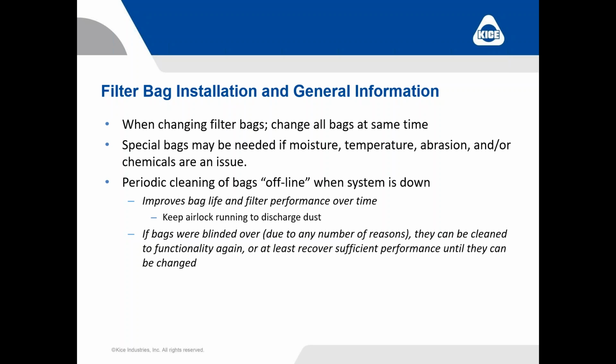And what that'll do is at the end of the day, you let that cleaning mechanism run for a while. Tomorrow when you start up, you're going to have a good, nice set of clean bags. It's going to hopefully give you a lot more bag life and functionality out of that filter. Now, about the second most important thing when talking about that is to leave your discharge airlock running when you're running the cleaning mechanism offline. If we're knocking the dust off of those socks down into the hopper, we don't want to just let that dust sit there overnight or over the weekend and create a plug or create a bridge. We want to keep that airlock running.